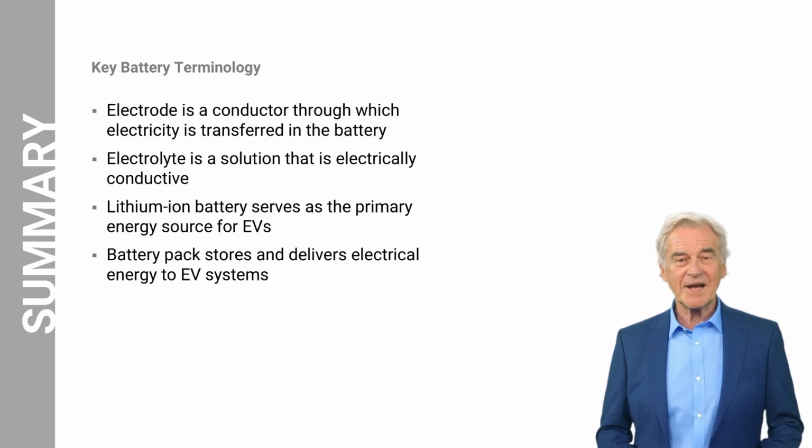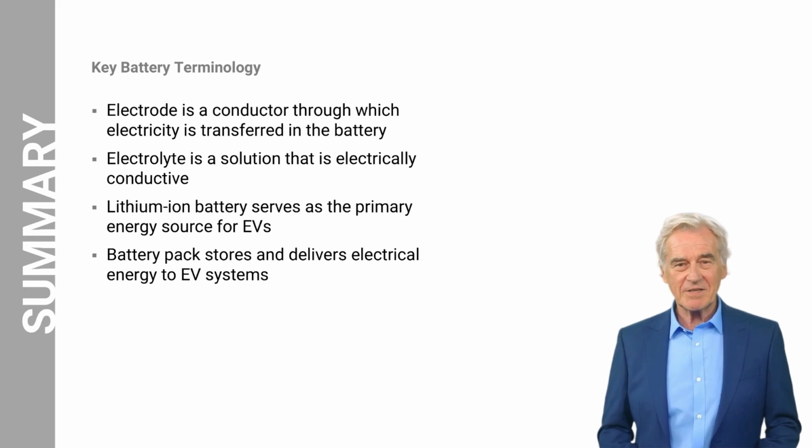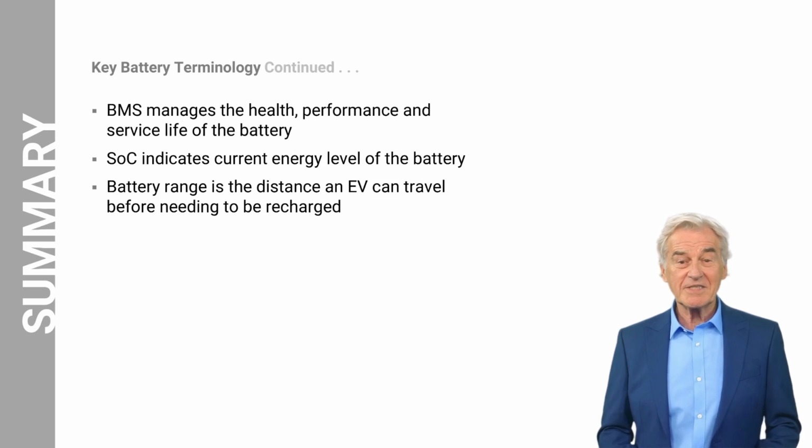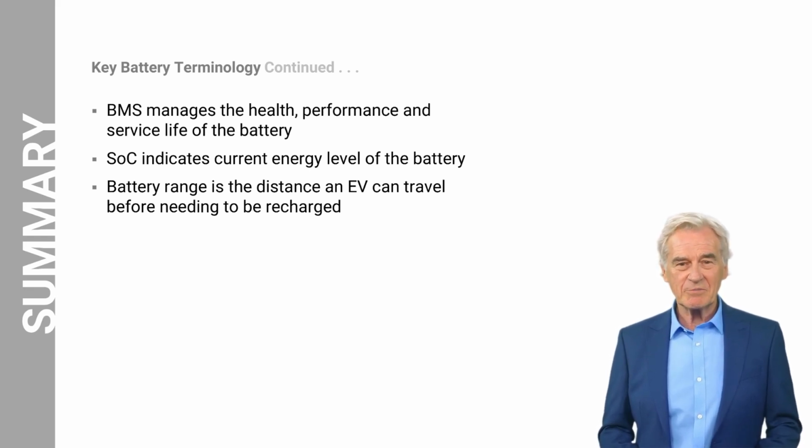The lithium-ion battery is the primary energy source for EVs, storing and delivering electrical energy to power the vehicle. The battery pack consists of interconnected lithium-ion battery cells working together to store and deliver electrical energy to power the vehicle. The Battery Management System, BMS, manages the health and performance of a battery and ensures the safety of a battery pack that is composed of multiple cells.